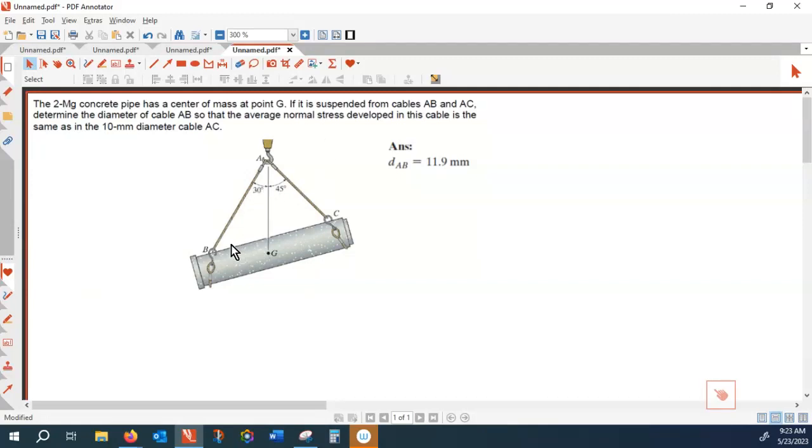Again, you have to find out the tension inside each cable. So that is my free body diagram. If I take the entire thing as an envelope, there will be a force of mg acting down. So I know that hook is taking mg.